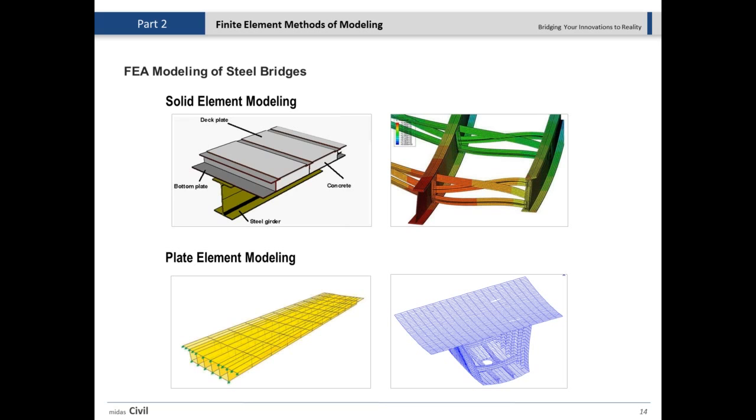The plate element is actually very helpful and sits in between the beam element and the solid, and it's giving us very good results, acceptable for the code, and I can say very accurate results. When we are using a plate element, you can model the webs, the flanges, the concrete topping, stiffeners, all of them with the plate element. You have to ensure there is a nodal connectivity between those, which means they are working together. And you can do any changes you have.